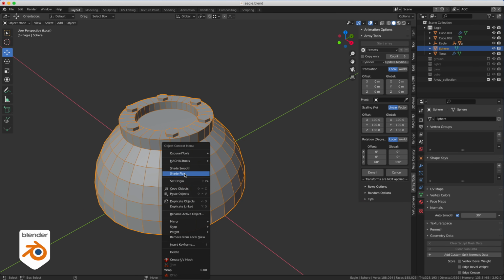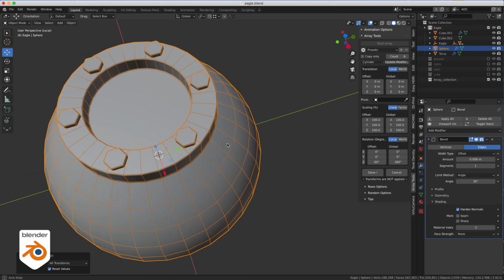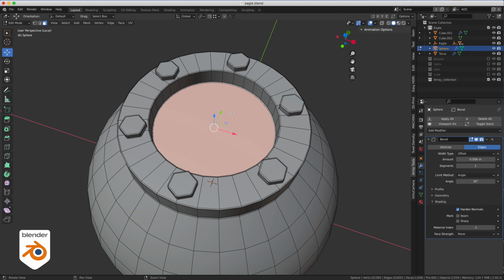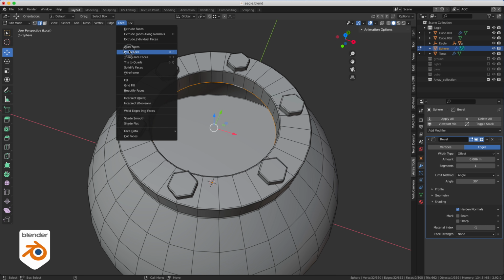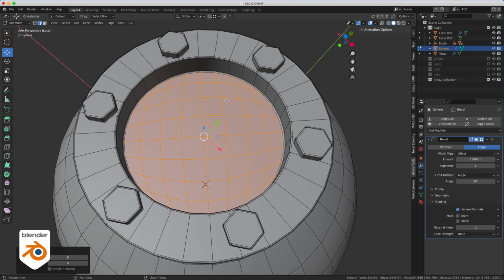And we do the same as always, so smooth surface, auto smooth, bevel modifier, and subdivision modifier. If you want to get rid of this n-gon here, you can just simply delete it. Then you select the edges and you're going to do a grid fill. So select all the edges. Again, you press the shift option. You do your grid fill. It's in the face menu. And now you get this here. But, it could be better. I don't like the way the topology is done when you do this.